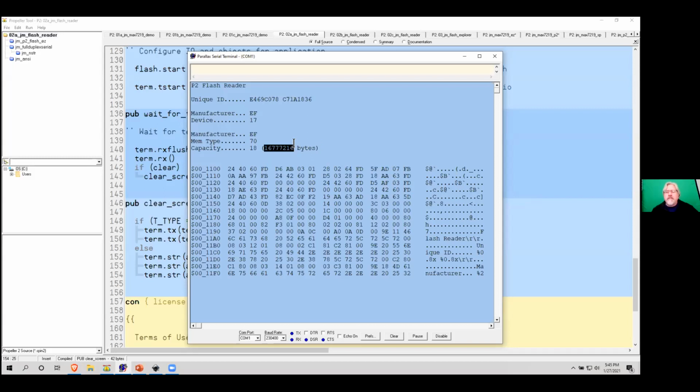Remember on the Propeller 2, we would normally put a 64K EEPROM on there. Now we've got a 16 megabyte flash. Yeah, I'm just thinking with Blockly, we could write to a small number of cells in the EEPROM before we cause trouble. That was my only experience writing to the EEPROM. Yeah, people get very worried about cell damage. I really think you'd have to do something with an automated process constantly writing to a cell.